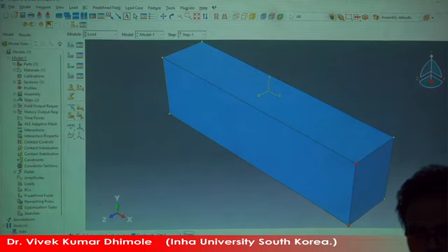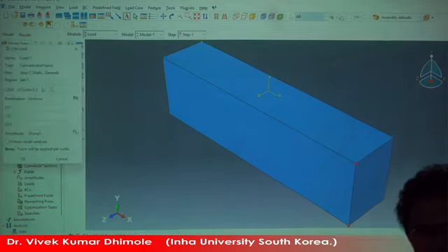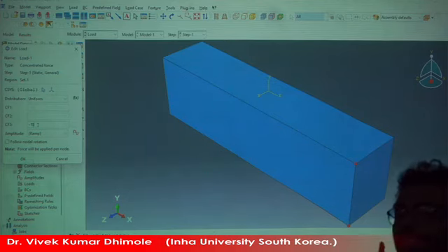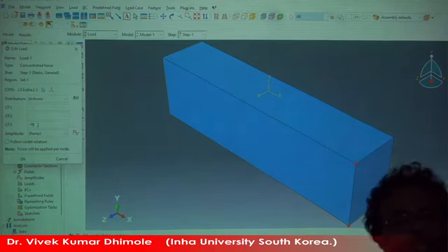So we have the two points and you apply the load, okay, and you can apply the concentrated load. See the direction, Z direction is the third direction, right? So apply minus 10, and what is the unit? We are applying megapascal, so the unit will be Newton per mm square, so it will be Newton, right?